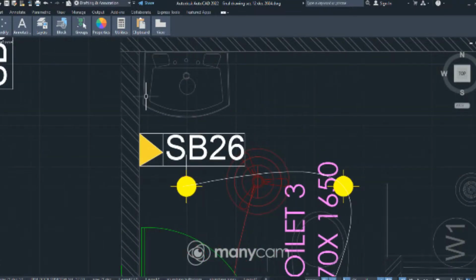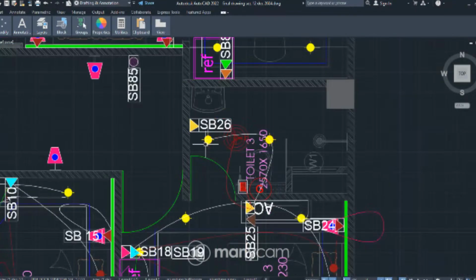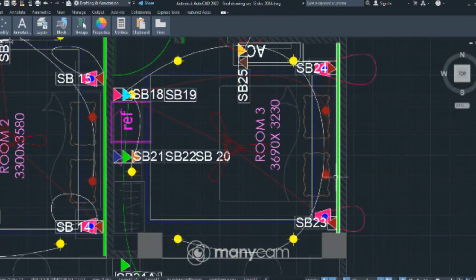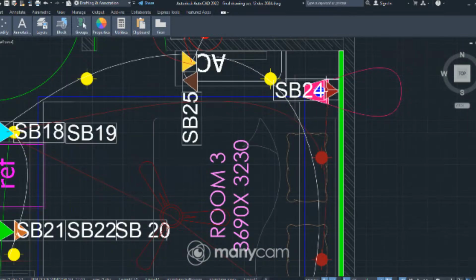This switchboard will be having a switch and socket for your shaving and 500 is fine, a switch for hair dryer and your shaving trimmer. So one switch will be given inside for that. Fan is given here, so yes, this is fine. Since fan, switch and socket are given on this switchboard, the two-way light we can give here.